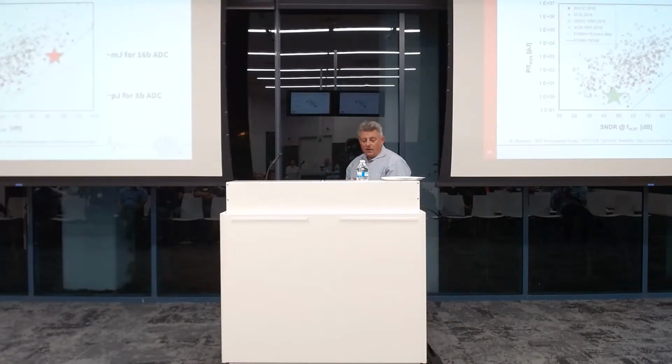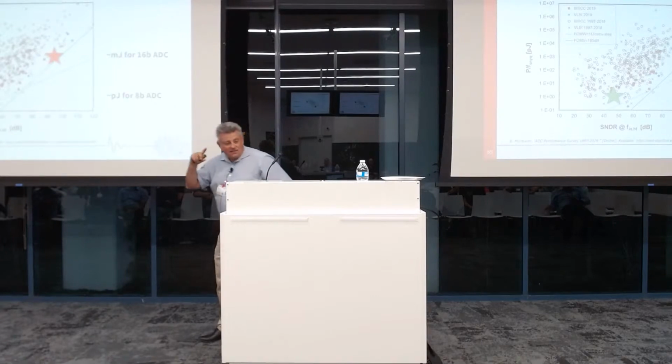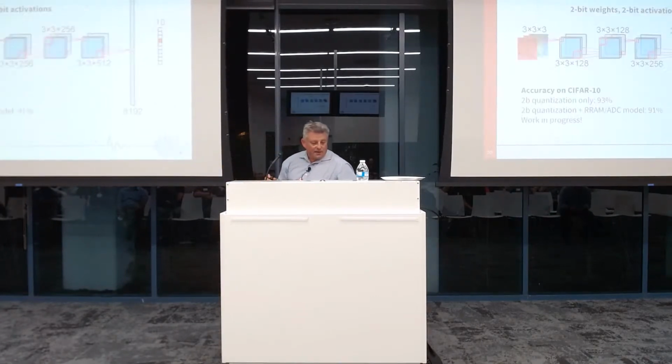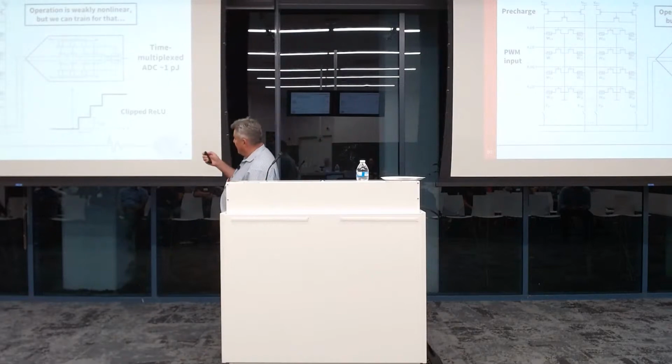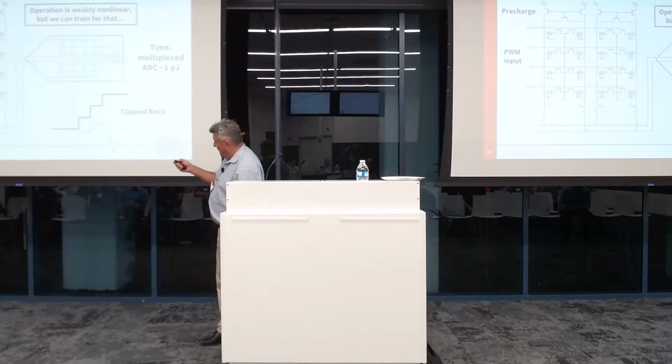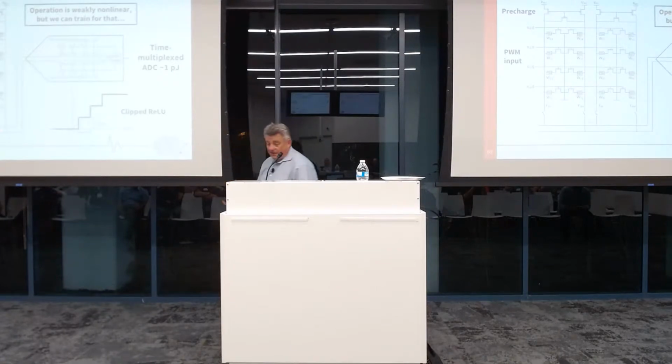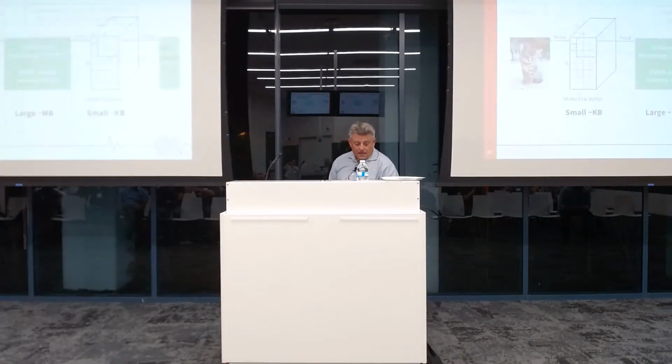So the last point I want to make here really is that, for those who are not completely familiar with it, these ADCs, if this technology actually ends up winning in some way, these kinds of ADCs will actually be very important, because if that energy is too high, then it doesn't amortize well enough across these thousands of columns, then you're in trouble.